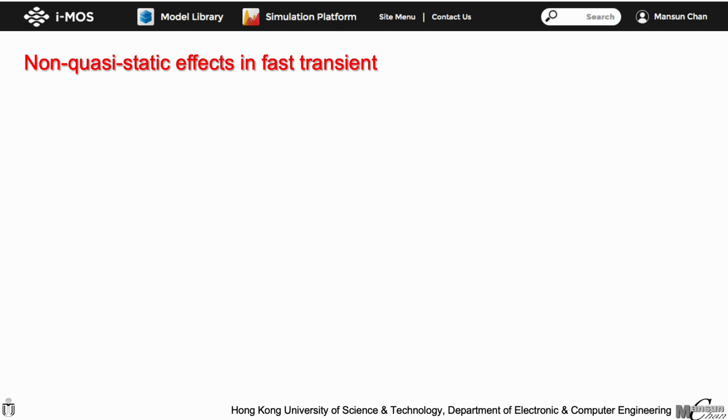Strictly speaking, it is incorrect, as all frequency domain simulation is based on steady-state biasing point solutions to linearize the RC network. That is, the nature of the simulation is under a quasi-static setup. If the output fails to match physical data at a high frequency, it is just because the lumped circuit model does not have enough circuit elements to capture the distributed nature of the channel.